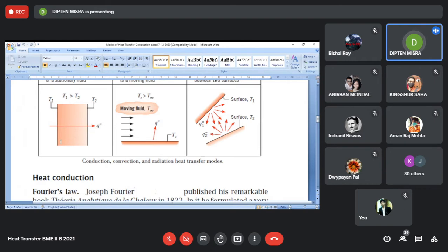So when things are negligibly small, we can assume them as equal to 0. We can assign a value of 0 to them because those quantities will be very small, negligible, insignificant. We can neglect their magnitude and we can say the heat flow along y is 0. We can say heat flow along z is 0 and there is only significant amount of heat flow along x, that is across the thickness of the wall.